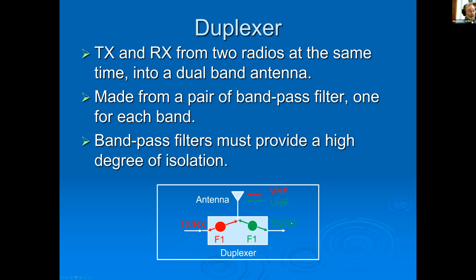On the right side of the picture, you can see you have another transmitter receiver operating through a really nice bandpass filter through on the UHF band. And again, these filters are built where you have a pretty darn good level of isolation between this. So the UHF transmitter does not interfere with the VHF receiver. Typically, these are run on a little lower power. You'll see these guys good for anywhere from 5 to 25 watts.